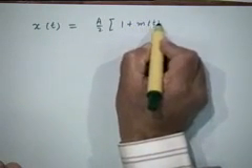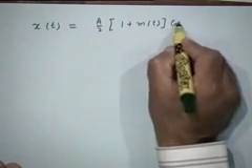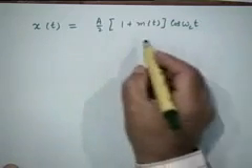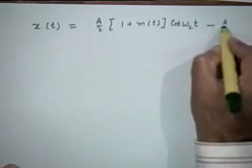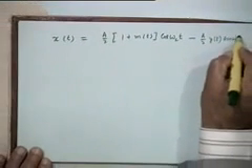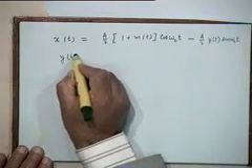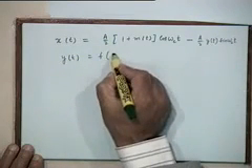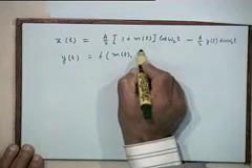Once again, this carrier part which I have introduced is because we want to be able to do envelope detection in the same manner that we did for SSB. So this part will be the same as we have for the SSB, plus of course there is a carrier that I am introducing here, minus A/2 into some low pass signal y(t) sin ω_c t, where y(t) will be, we will see soon, a function of both the message signal and its Hilbert transform.